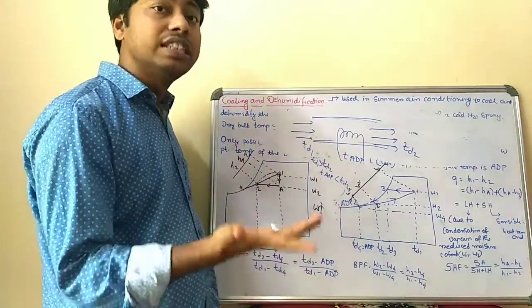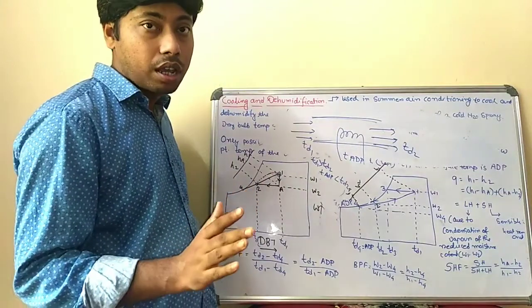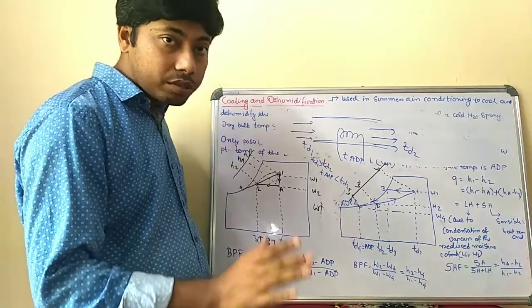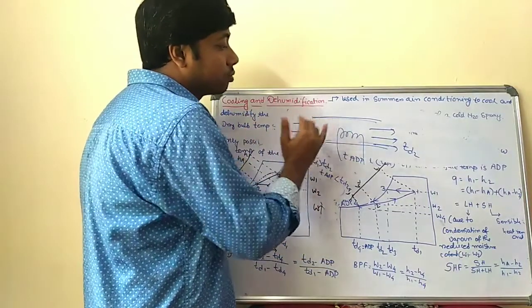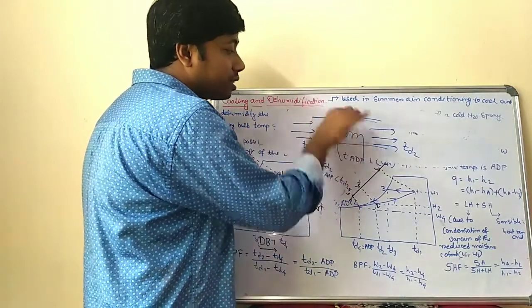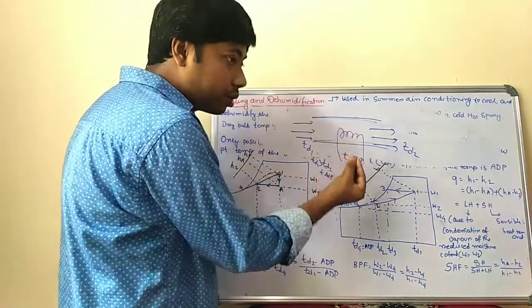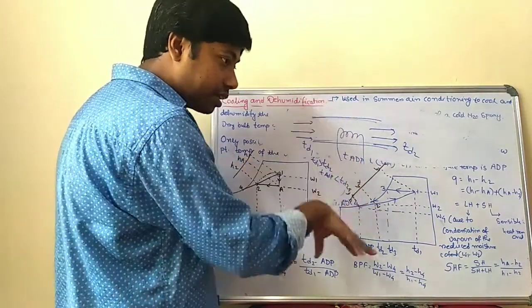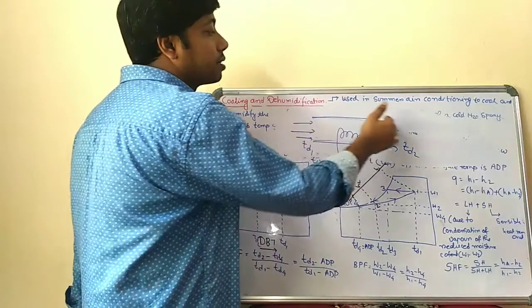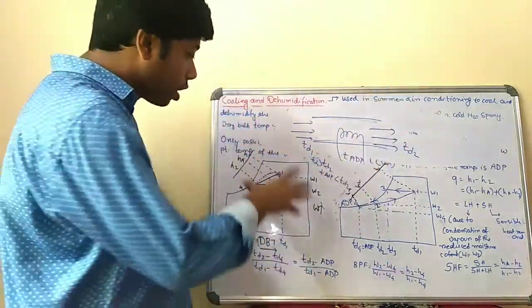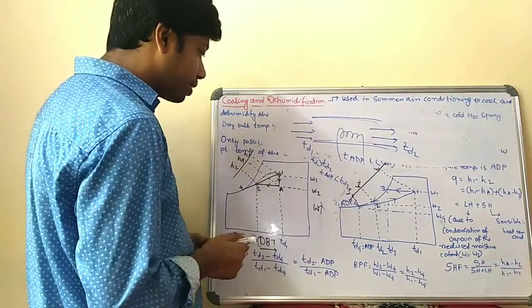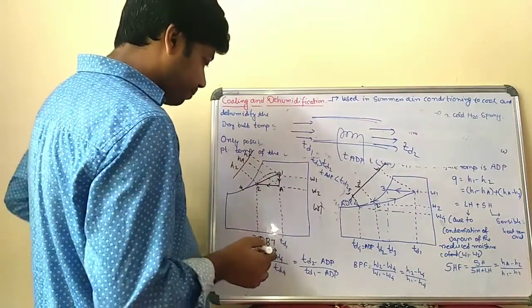If it is not, then dehumidification is not possible, because dehumidification is only possible when the condensation process takes place, when the entering air contacts this apparatus dew point temperature, so that some liquid droplets condense and drop out, and the remaining air passes through, so that the dehumidifying as well as cooling process takes place. So in this process, the cooling and dehumidification process takes place.